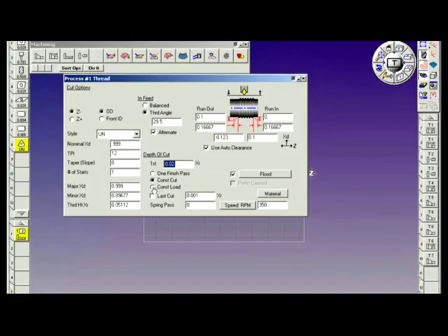Or you can use constant load, which is preferable, I believe, because it keeps the load on the spindle the same throughout the threading operation. It diminishes the depth of cut the deeper the tool is engaged in the work. Take my first pass at 15/1000ths. All the following passes will diminish in depth up until the last cut.